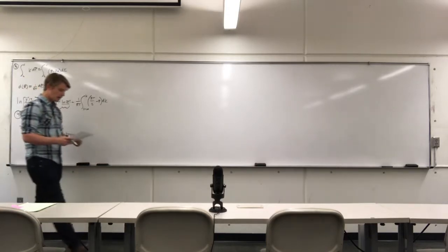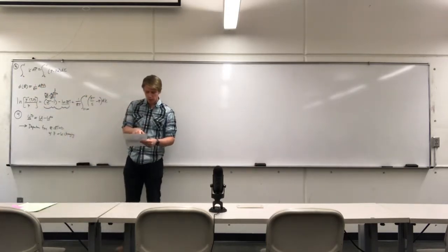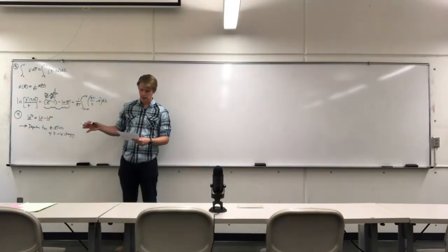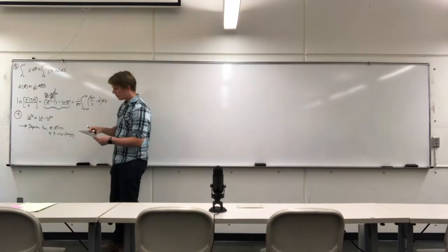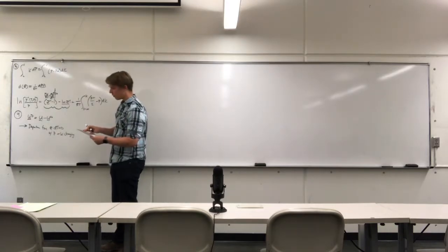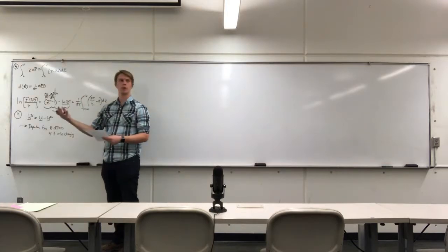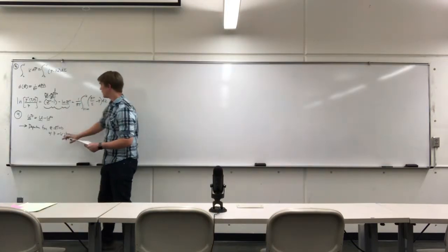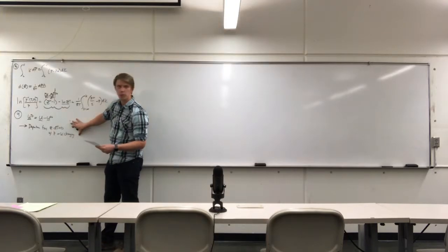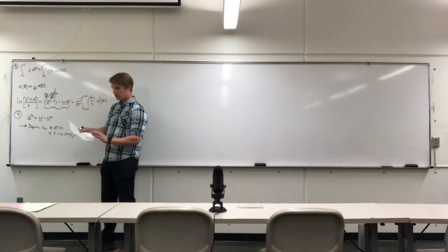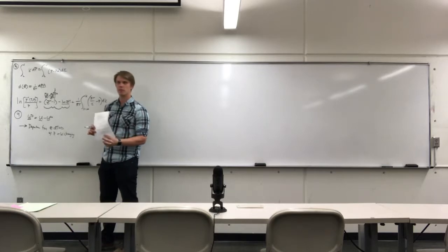Now the idea behind this is more or less the last part of the problem. In this I ask you to calculate the departure function and the U, H, and S for ammonia transitioning from an ideal gas state at temperature equals 0 to a pressure equal to 10 atmospheres. So the idea here is I want you to first derive the expressions using the van der Waals equation of state and then apply it. You'll also notice that on question 6, we're using the van der Waals fluid to do the vapor-liquid equilibrium of ammonia.